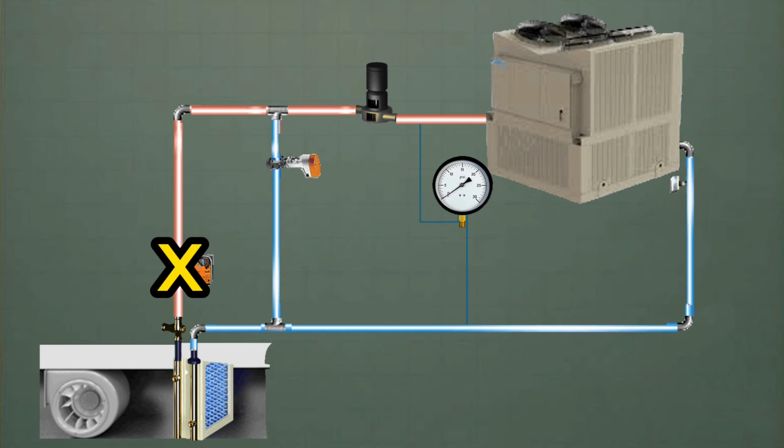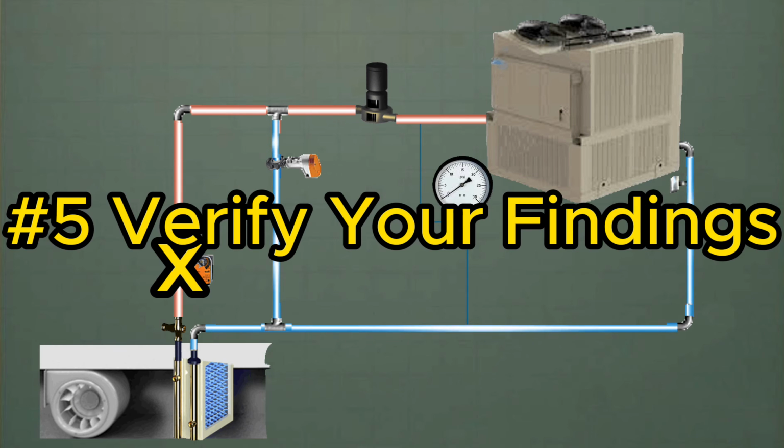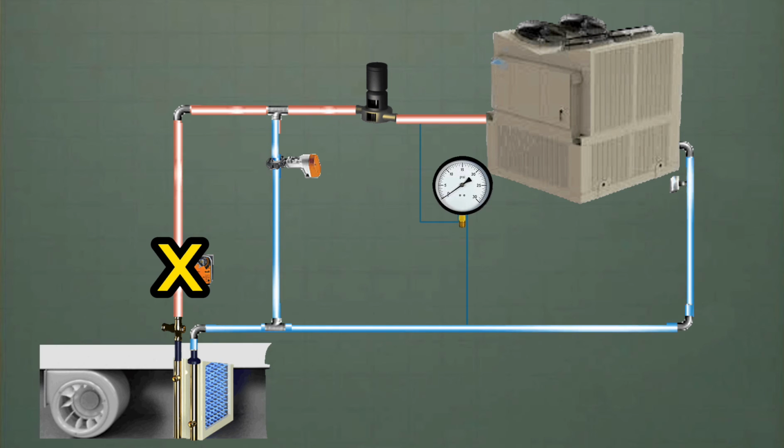And again, I am 99% sure at this point, but I'm going to double check the flow curve just to be sure, because some customers are finicky and some customers don't like to accept that something has an inherent problem. The same thing with the bypass valve, or any valve or anything that flows water, there's a flow curve for it.